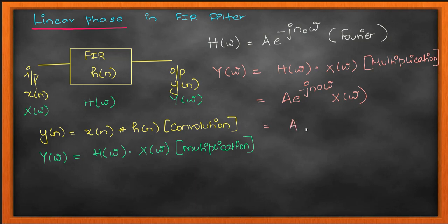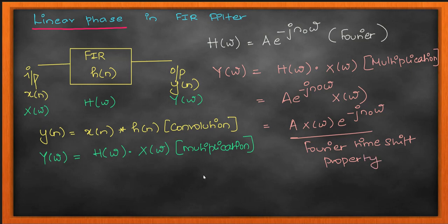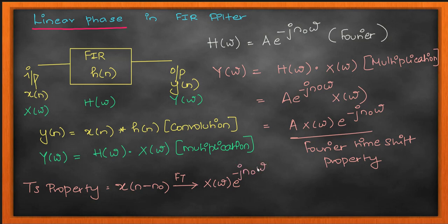This is very important because if I have variable delay at variable frequencies, then I have big problems, because phase and frequency are related. The derivative of your phase is given as the frequency. So when your phase is not changing constantly, or is changing variably, then your frequency is also going to get altered, which means the filtering itself will change the frequency of your output. It should not happen, right? When I apply an FIR filter, it should not change the characteristic of my input signal, and that is taken care of by this linear phase.